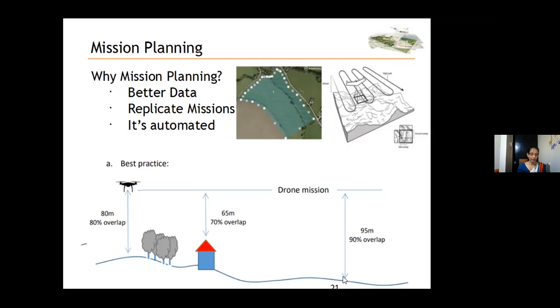Another thing you should check is whether this is a good project for drone photogrammetry. A very large project having more than 500 acres or 1 lakh of photographs, dense vegetation, and tree cover where the ground underneath the trees is not visible are not suitable and are considered bad projects for drone surveys.